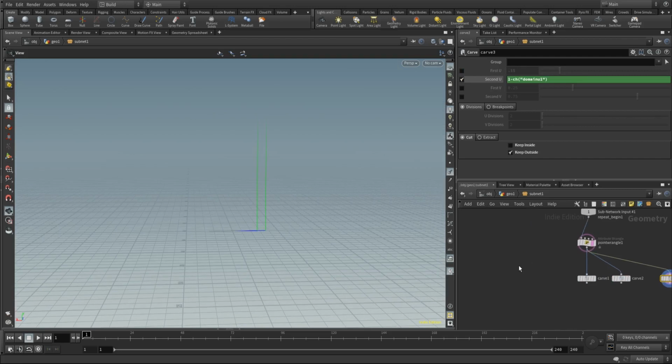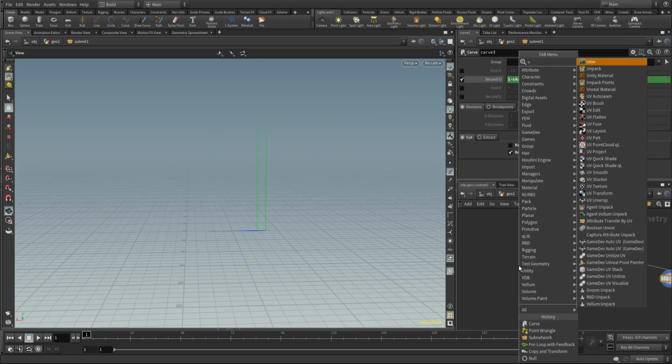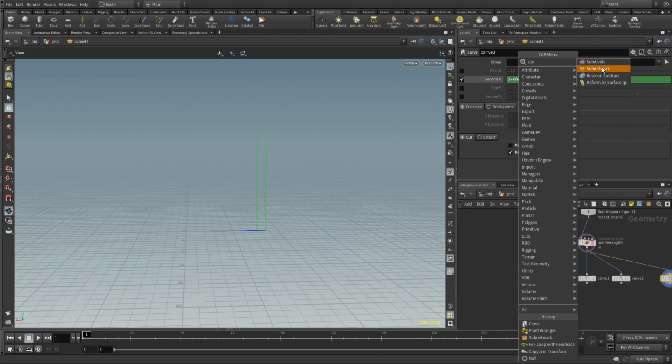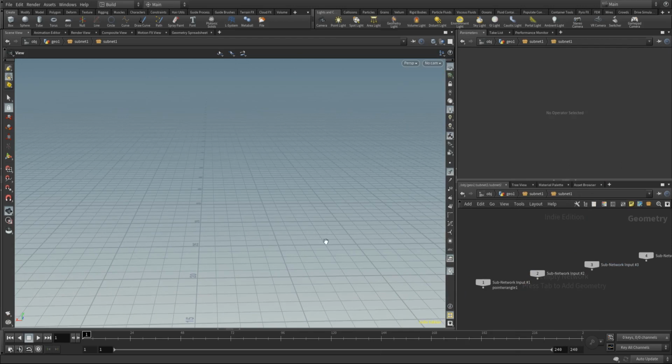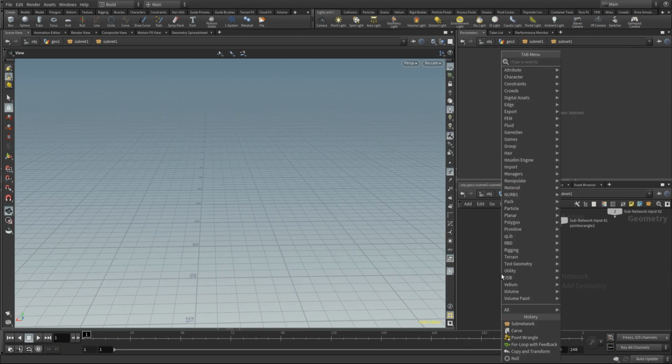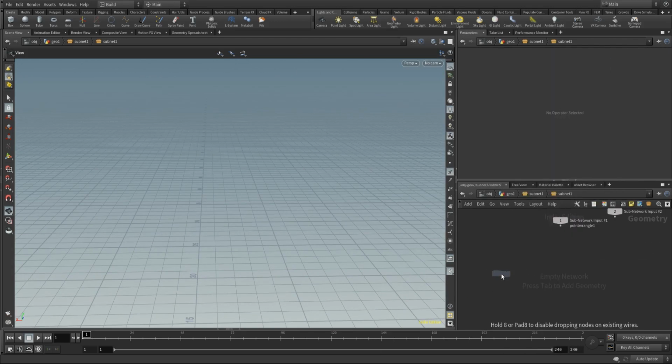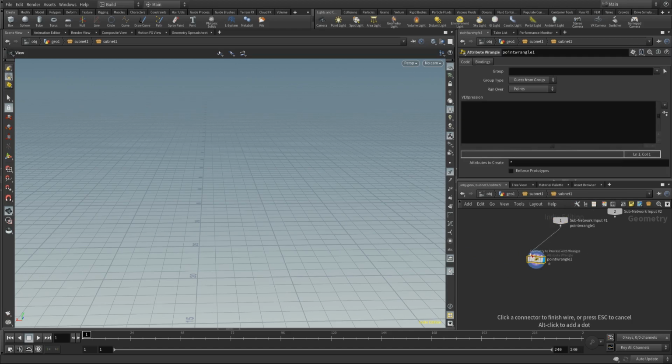Really nice. Then I'm going to place another subnet. And inside of this subnetwork, I'm going to create a plane out of this thing. So with a pointer angle, I can access the height. So we have the height and we need to offset this primitive by the amount of the height in the direction of the up vector.